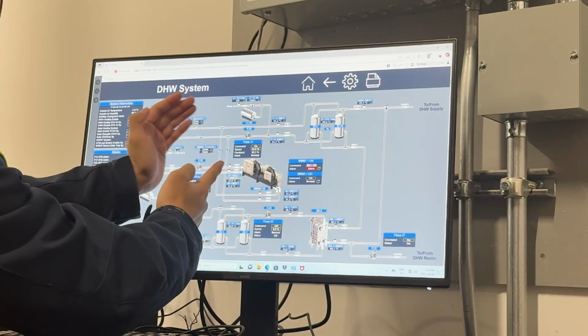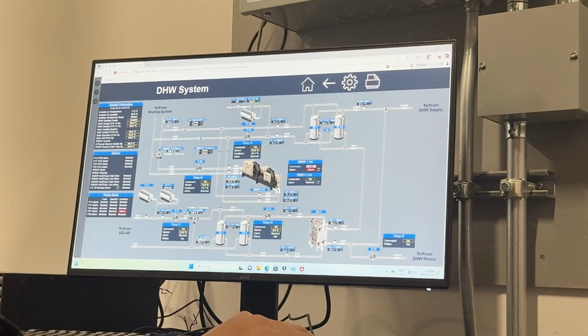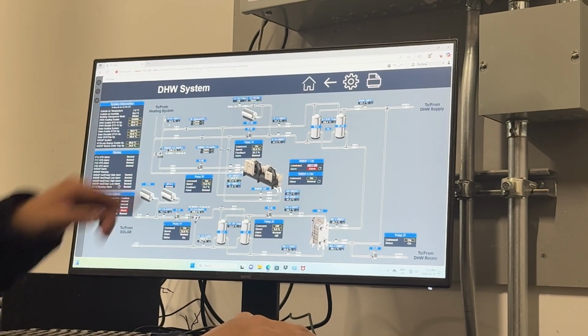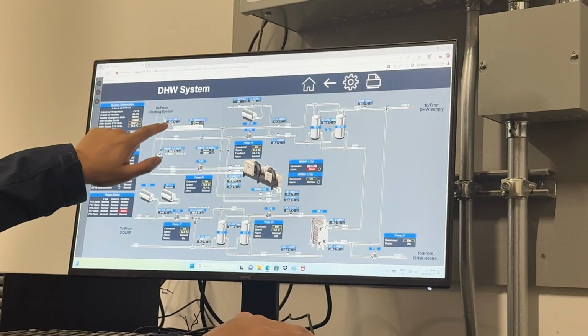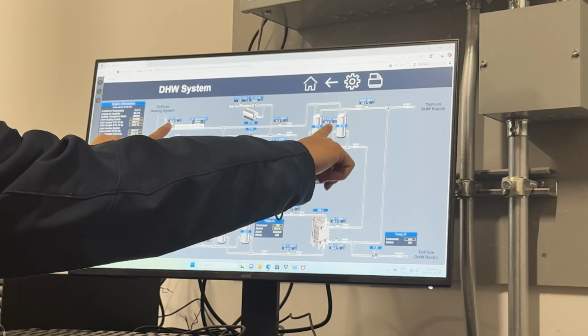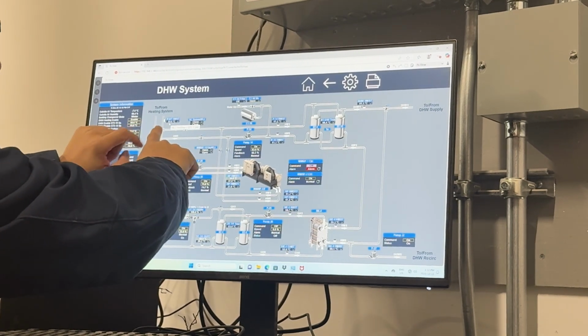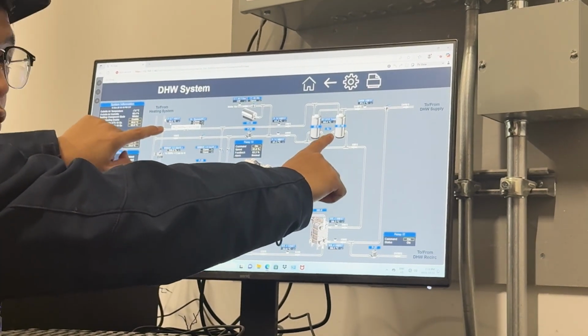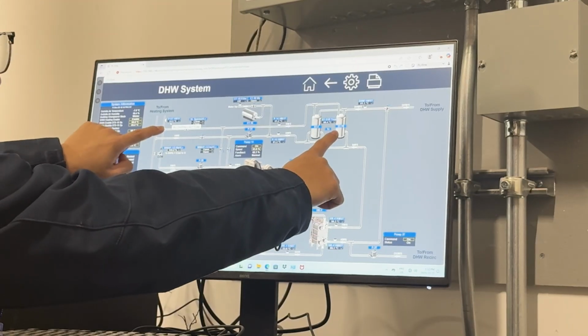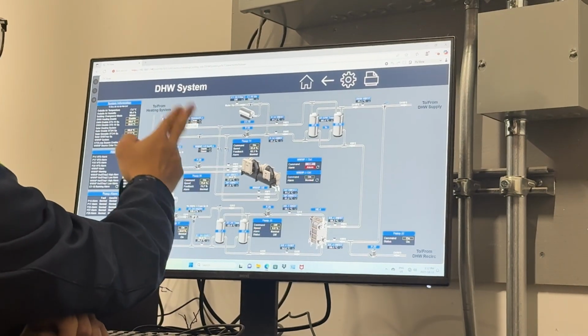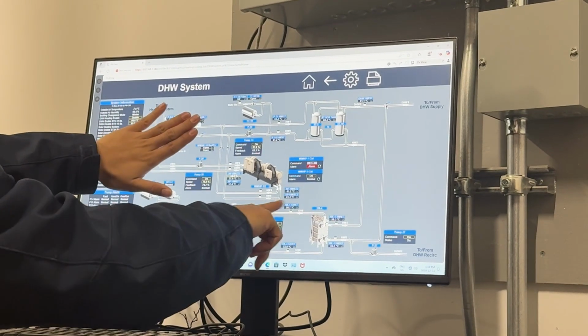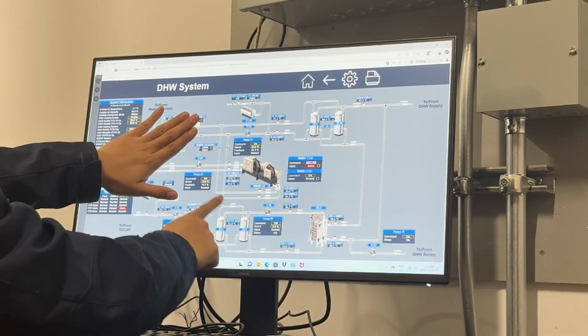So what that does is, the boiler loop temperature is only 56, right? It's only 53. It's only 52.6. But we want this temperature to be at 60. So the boiler loop is not capable to provide enough heat to storage tank 5 to 10. That's why we have this bypass valve closed. Right now, all the heat is coming from the water-to-water heat pump.